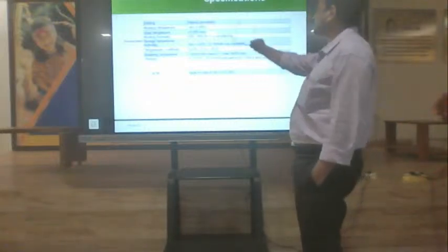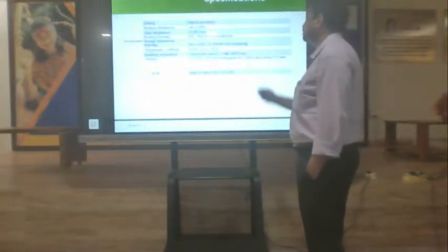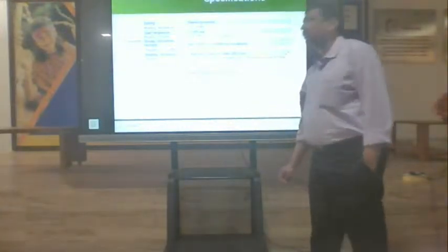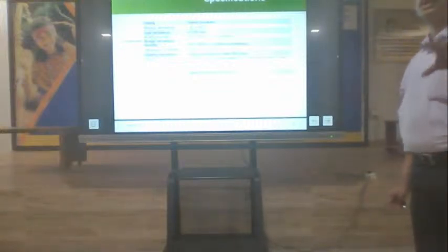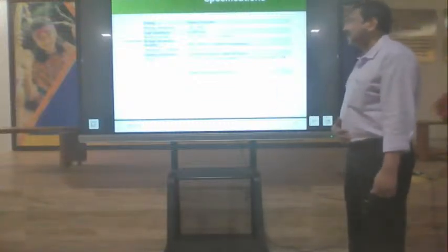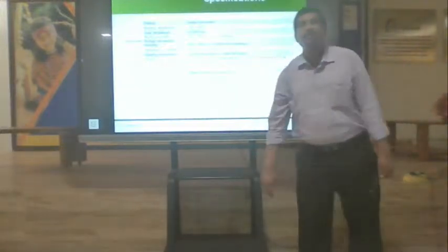Then you have the humidity, then the storage temperature where you can store it. Why this is important: if the devices don't have proper storage conditions, they start rusting. Once the device starts rusting, you cannot connect the terminals, there will be a bad contact, and then it doesn't work. Another is the vibration. Whenever the device is subjected to excess shocks, there should be no disconnect, so it should survive those vibrations.